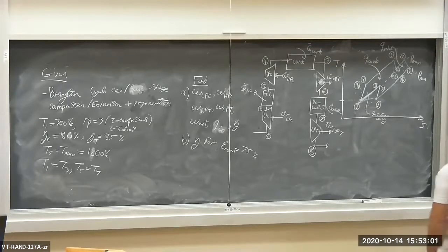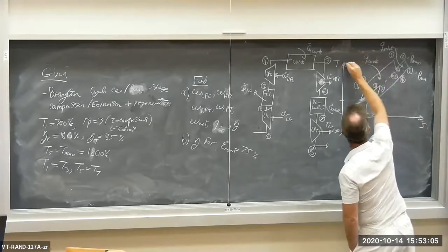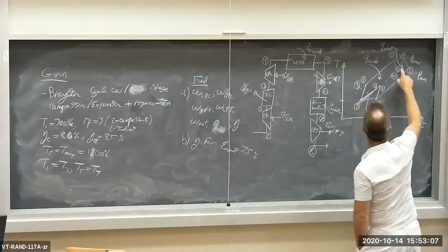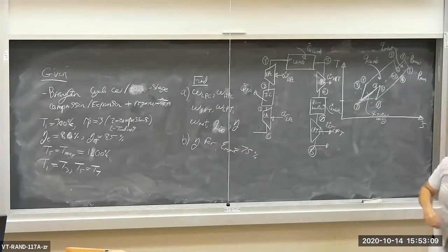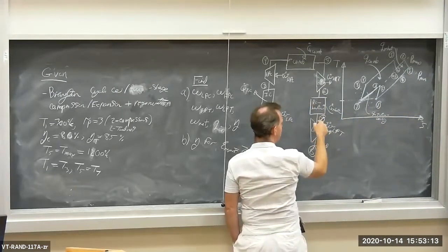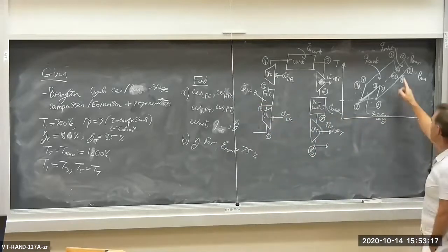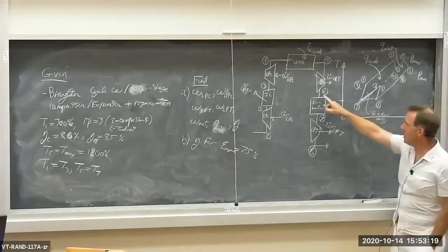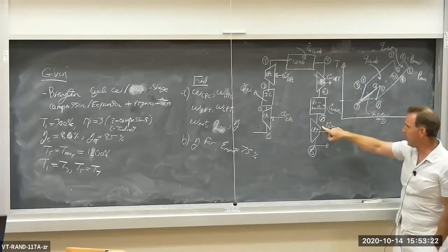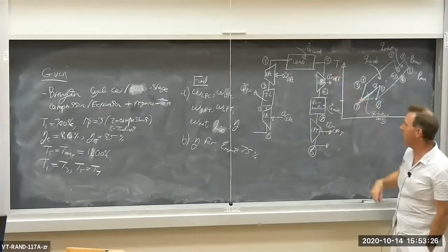Likewise, we are adding just enough heat in the reheater. So the reheating occurs between the high pressure turbine exit and the low pressure turbine inlet. We're adding just enough heat to bring the low pressure turbine inlet temperature back up to the maximum temperature, T5.